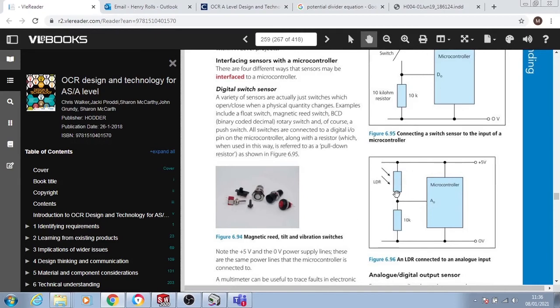So if this has got no resistance, this is going to be 5 volts. So the voltage is just going to go straight in, uninhibited like that, and then this is going to be showing the full resistance from 5 to 0 volts. Okay, so equal resistance, it shares this voltage. If this is like 1,000 ohms and this is 2,000 ohms, then this is going to be at 2/3 of the voltage, 3 and something volts. Okay, and that's pretty much it.